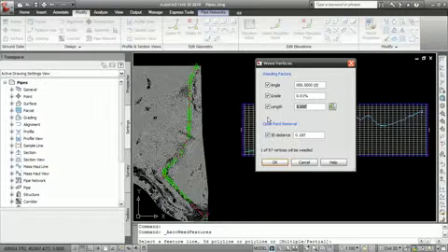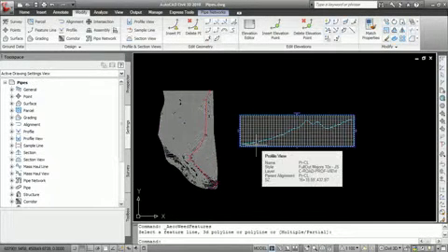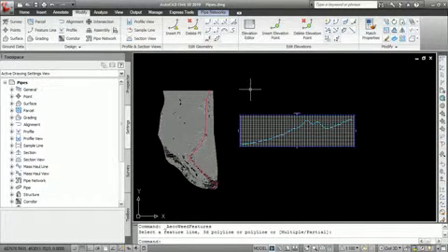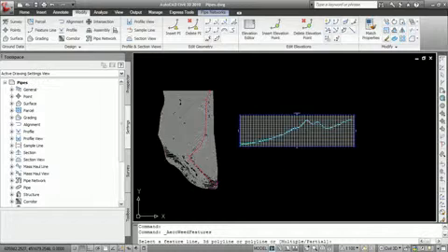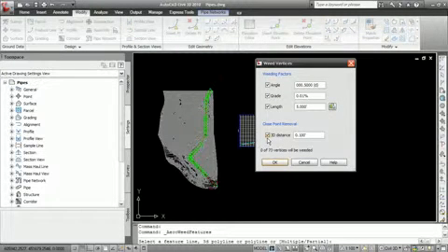This time I'm going to increase the length just to maintain a set number of vertices still. I'll increase the grade to 8%. And this time I will use a 3D distance so that it will remove those clumps of vertices. Before, when I had many vertices, this might have done too much damage by removing too much. Now that I don't have as much, it's safer to use the close point removal. So now, I should be within that 75 number. And to check, if I go back to the weed vertices command, I can see that I have 73 vertices left.